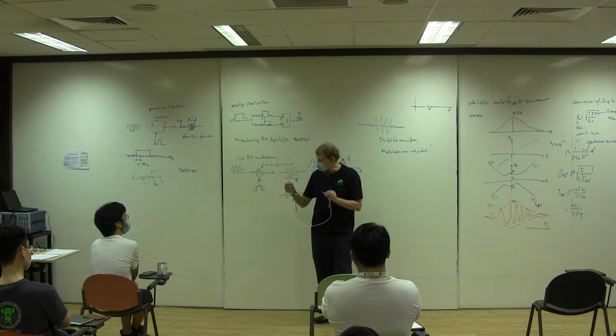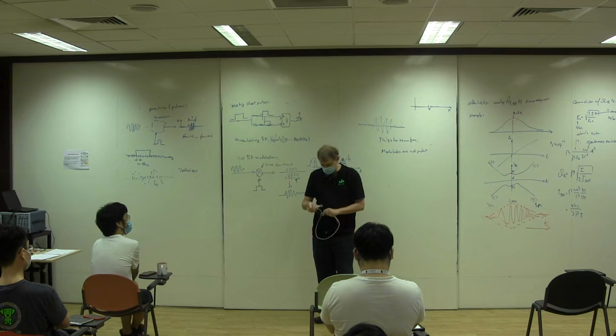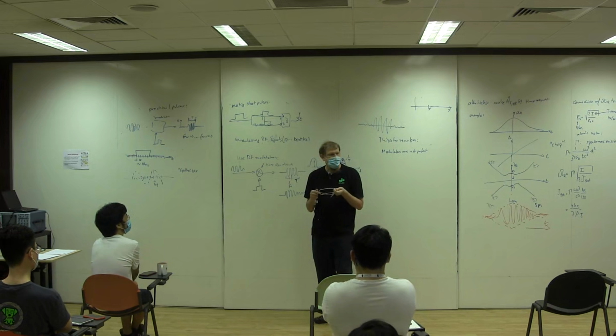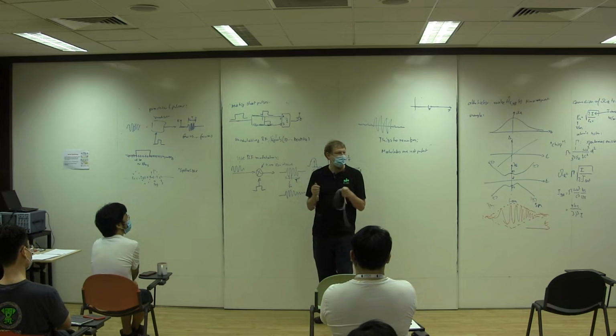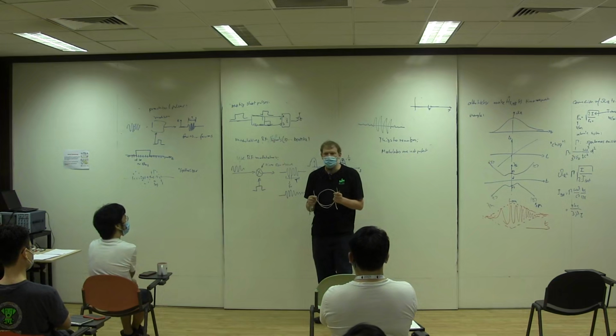Also, most of the coaxial cables that you work with have an impedance of 50 ohm. And that makes it a bit difficult to get some of the digital signals through them, which means like 3.3 volt signals or 5 volt signals. You can work this out: if you have a 5 volt signal from your standard TTL or CMOS device, and you would like to drive a 5 volt signal into a 50 ohm cable, you will need a current of 100 milliamps. Okay,